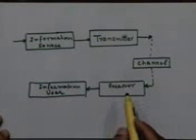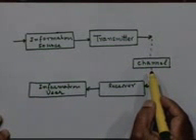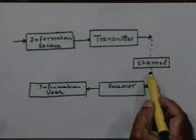Right? The job of the receiver, as I just mentioned, is to undo some harmful degradations that might have taken place while the signal was being transmitted through the channel. Also, additionally, it will try to amplify the signals, because typically the signal will attenuate as it propagates. But in addition to providing simple amplification, it also has to remove noise.